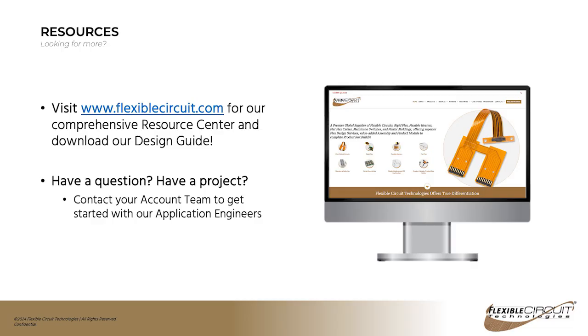What components am I able to utilize on a flexible circuit? Pretty much any component that you can put on a rigid PCB, you can also mount on a flex circuit. We do recommend for pretty much all components that you do have some type of a mechanical rigidizer also incorporated in.